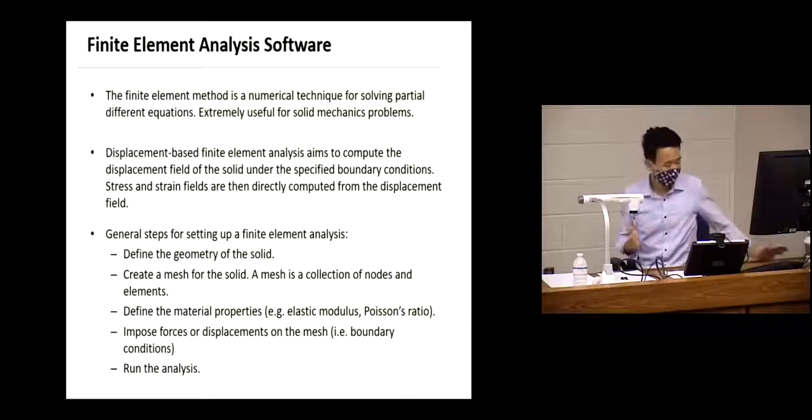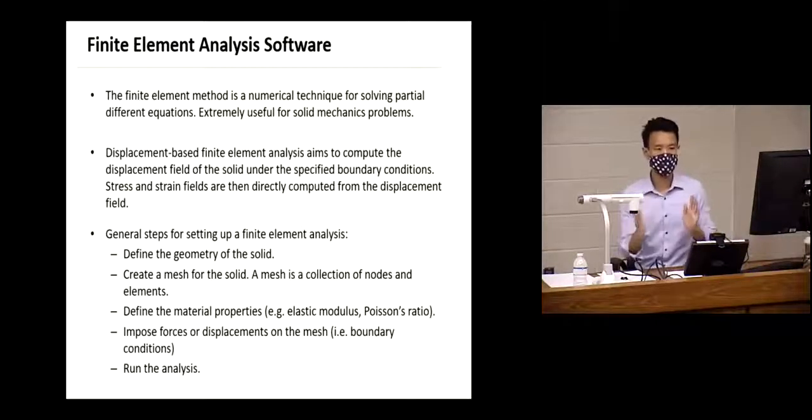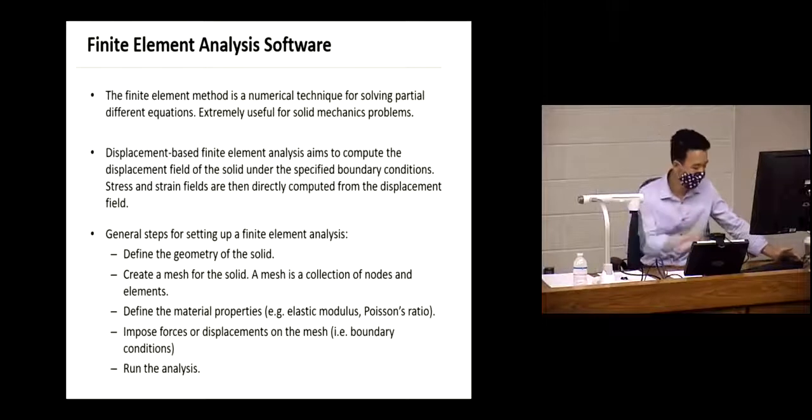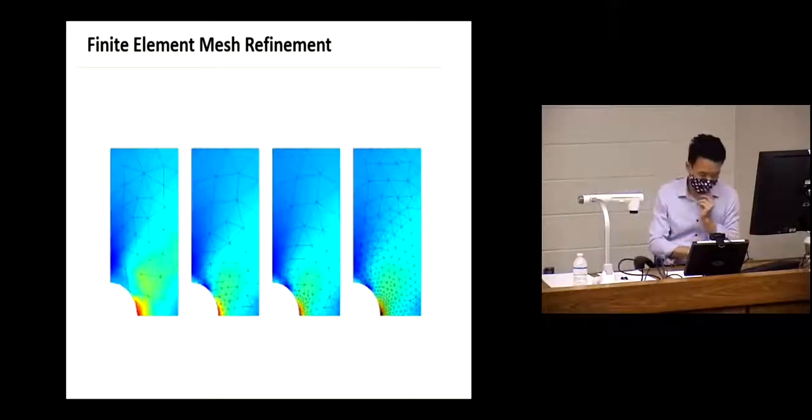So if you want to set up a beam bending problem for a complex geometry, first of all, let's see if your process works for a simple beam. Check that against an analytical solution. If that works, then you go back to your finite element model and start adding in more advanced geometry or maybe different material properties and so on. Okay, so it is critical that you check the analysis. So again, I'm going to put some more instructions in the homework to push you through that process. Now, one more thing about finite element, and then we are done.